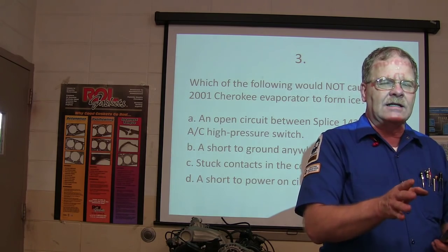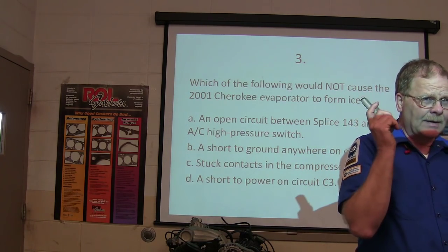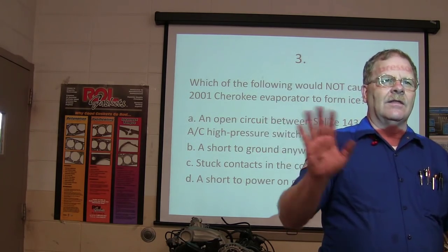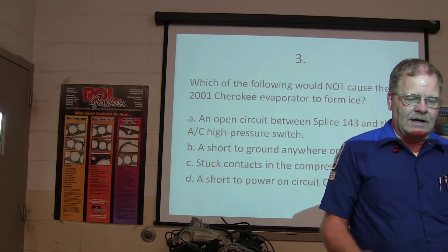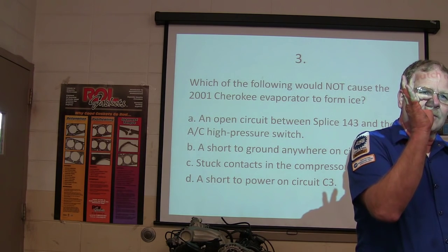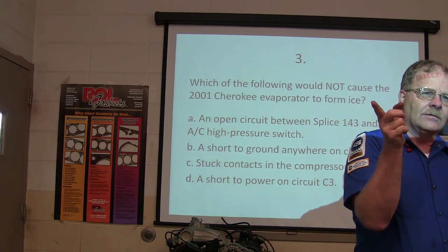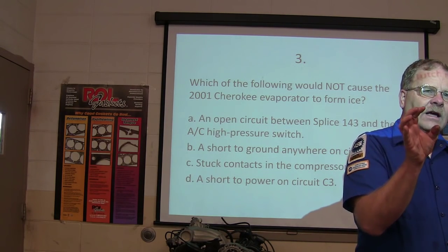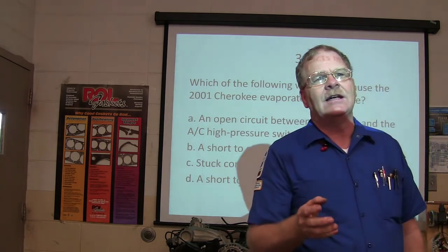It's because anytime you have a situation like that going on, like Gene Taylor's little pickup did it. He said, I drive down the road, I got air, and then I lose my air. There's no airflow, I can hear the fan blow, but there's no air. And so what we found out was the relay that drives the compressor was hung. And it was keeping the compressor on all the time. Now, on that Ford Fusion that I was talking about earlier, the control head on it is keeping the compressor energized all the time, even when it doesn't need to be.